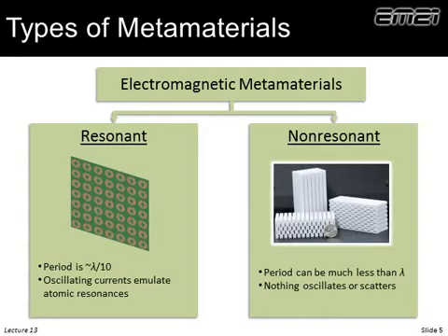So for these non-resonant type of metamaterials, the cutoff frequency really is where it begins to become resonant. So I'll say a tenth of a wavelength, although my experience is we can push that a little bit further, but the periodicity can be a millionth or a billionth of a wavelength, and they will work the exact same way. There's no current that's oscillating, there's no waves bouncing around. They derive their properties simply due to where the power is.